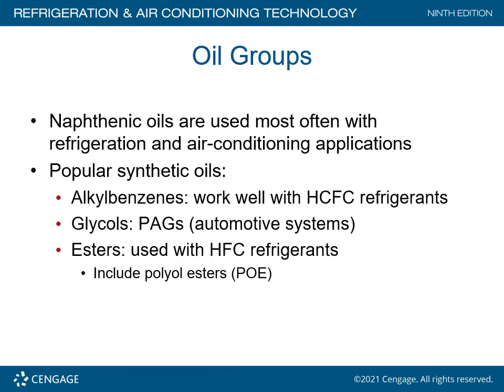And esters, which are used in HFC refrigerants, including polyol ester oil. So basically, all you need to remember are the PAGs. They're used in automotive applications. Alkylbenzenes are still available, but typically all compressors today utilize POE oil.